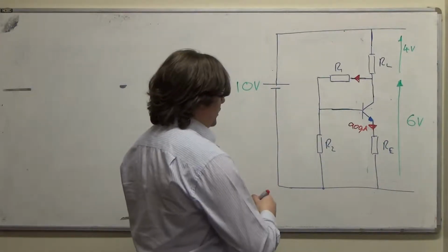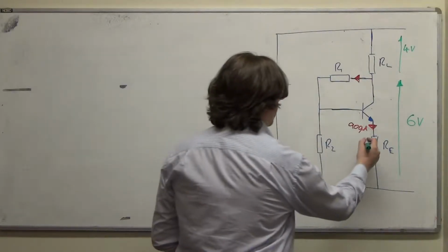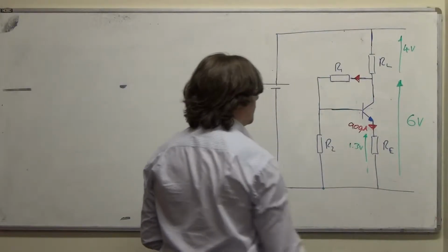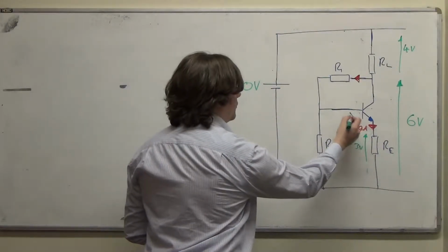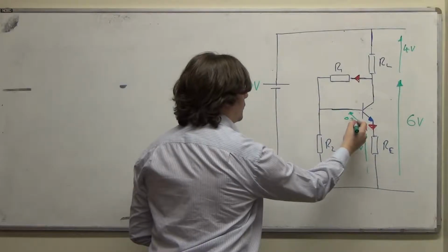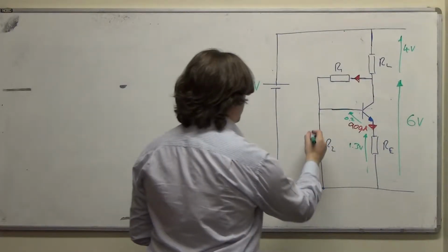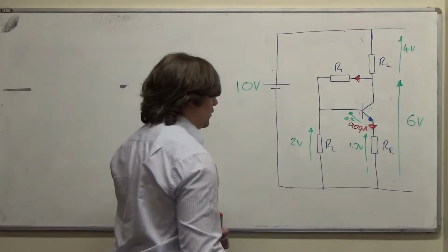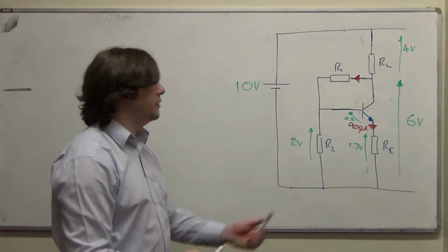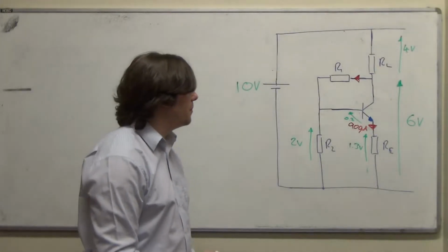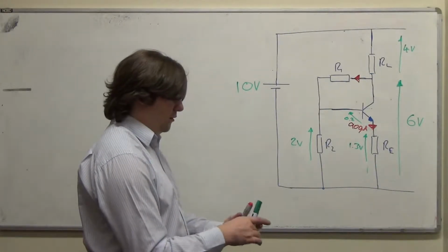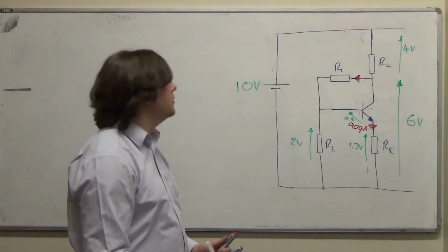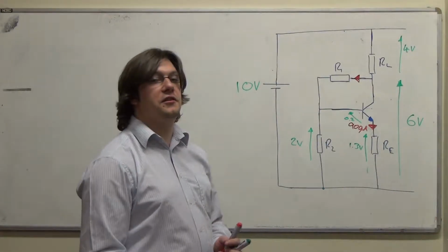And that we intend to arrange for an RE of 1.3 volts. And then we know we've got 0.7 volts there, because it's our VBE. So we know that VB is going to have to be that plus that, so it's going to be 2 volts. You might have got wind of the idea that I like VB being 2 volts. I can't remember the last time I set a question where it wasn't. Of course, this year could be the year.